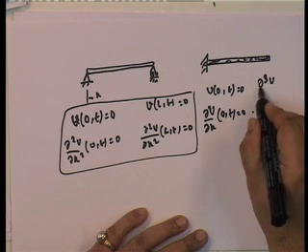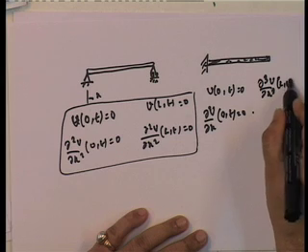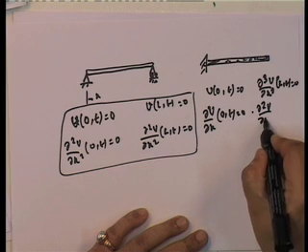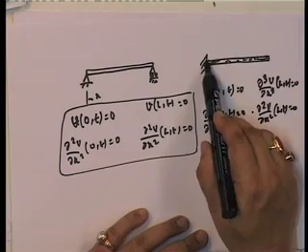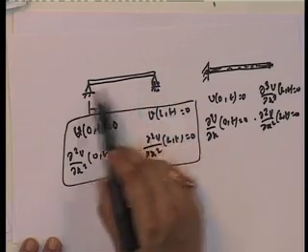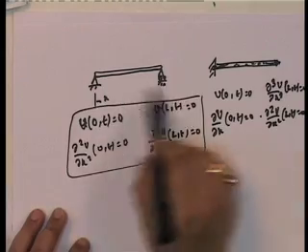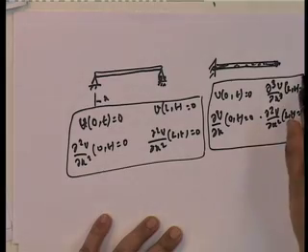So, d³v/dx³ at (L,t) is equal to 0. Similarly, moment is equal to 0, so d²v/dx² at (L,t) equal to 0. So here you have kinematic boundary conditions and force boundary conditions, both at both ends. So in essence, you always have to find out what your boundary conditions are in a particular case.